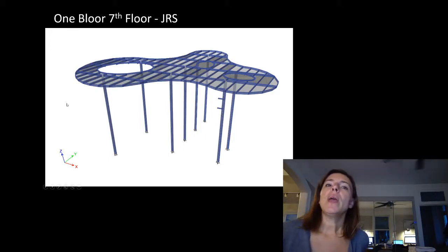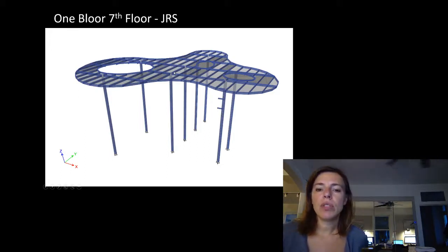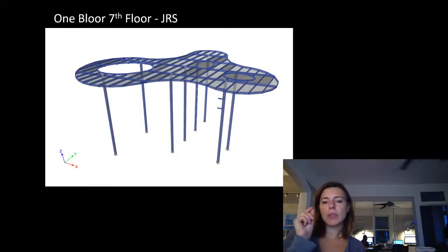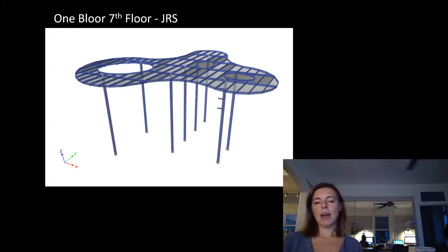When we have such slender columns like this, there's the opportunity for fabrication error. Nothing is going to be perfectly plumb. We're talking about small deflection or tolerance problems. If you remember back in Structures 1, and even in the refresher at the beginning of this, we talked about stability and the P delta effect, where if something moves out of plumb, that load is now eccentric from where it was supposed to be, which makes it want to push out even more. And then we check it again and see if it wants to push out even more.